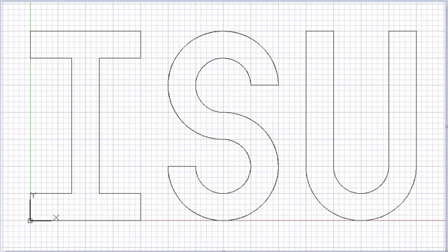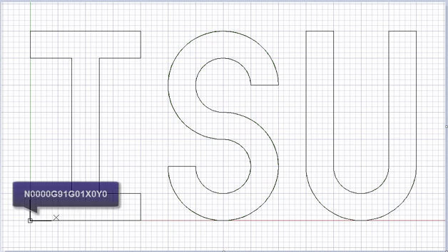This program will use relative mode, meaning for every new point, those measurements will be based off the previous point stated. Step 1. Looking at the first line of code, N0000, we will notice that G91 is used, meaning we will be in relative mode. The G01 used will tell the machine to go to its starting point, x0, y0, in a regular linear speed.